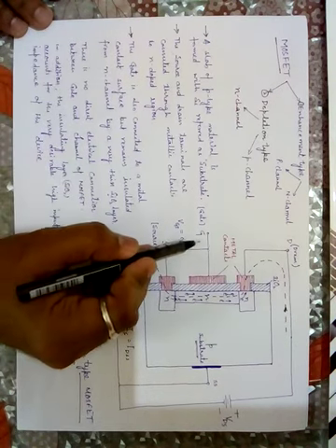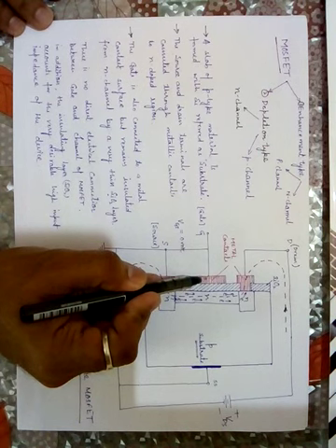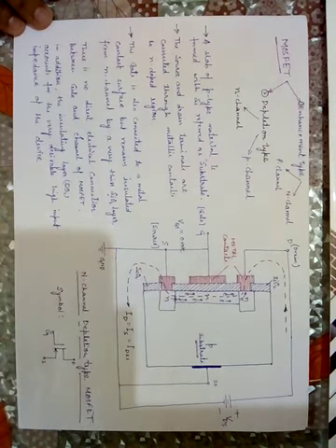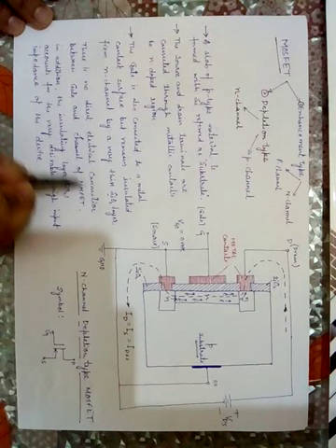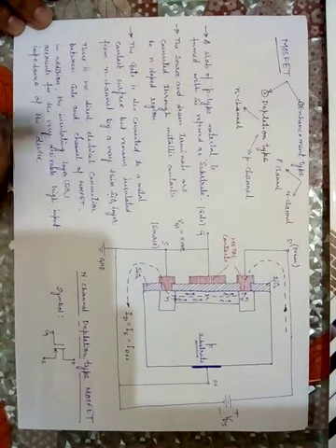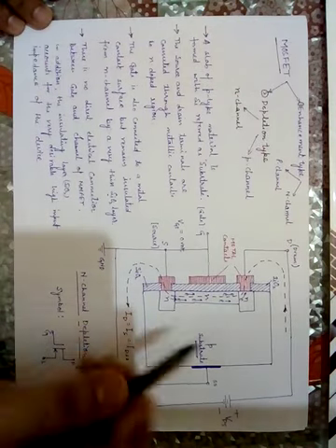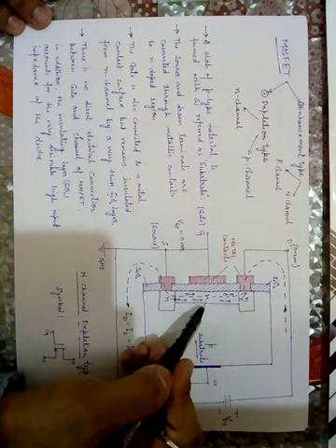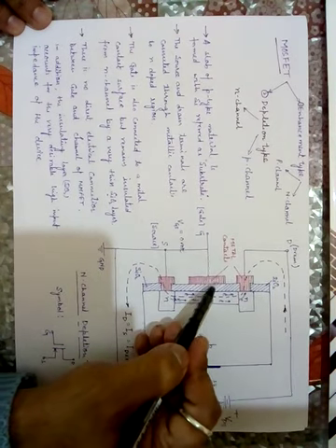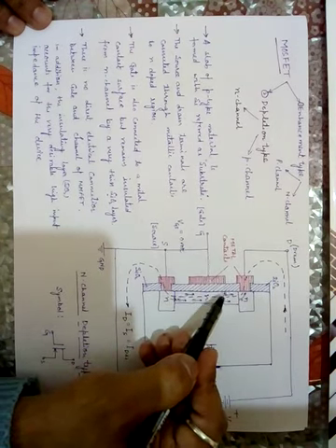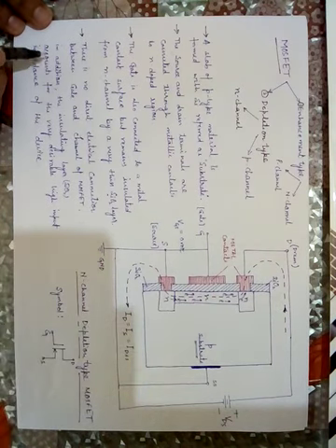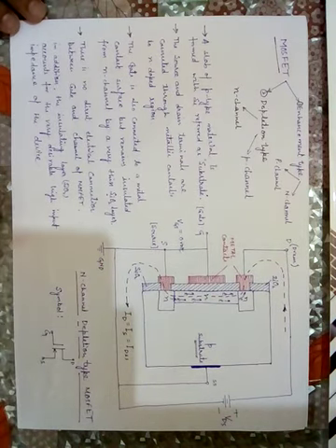So you have to remember that gate is not directly connected with the metal contact. It is silicon dioxide. There is no direct electrical connection between gate and the channel of the MOSFET. There is a two layer in between. First is metal contact, another one is silicon dioxide. Now in addition, this is a very important point.